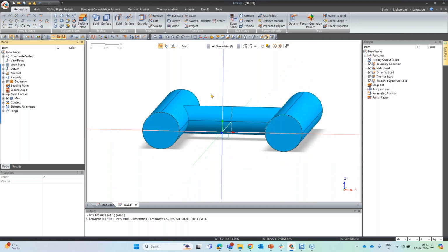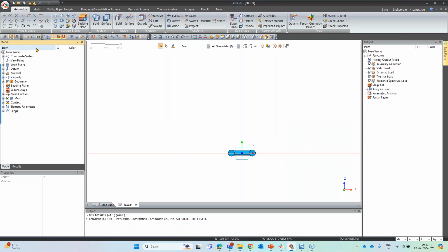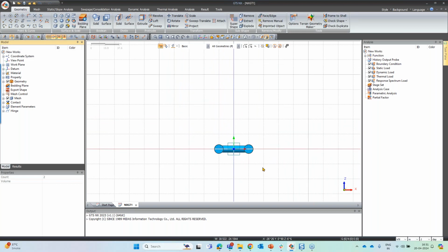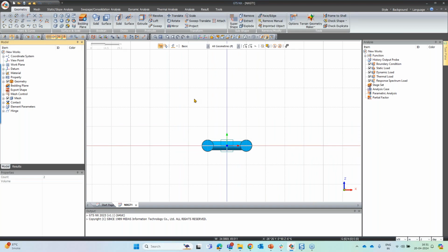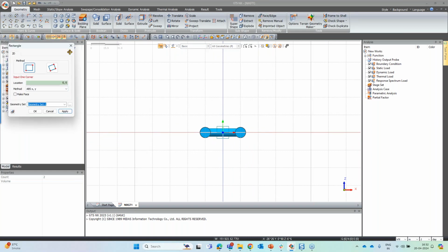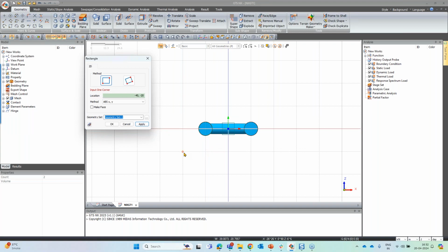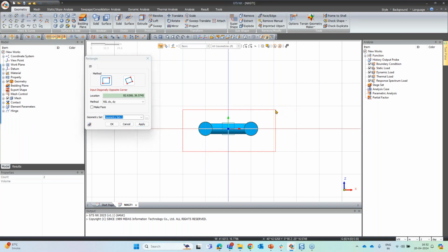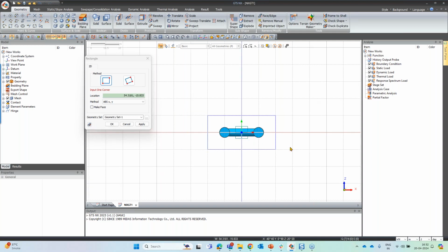Then, as we said, we are going to have the rock mass created, and this rock mass will be 200 meters in width and depth. So let's create the outline for the rock mass. So here we go. The inner rock mass which we are going to create is for a lesser mesh size, so that the stress transfer will be very good because the mesh size is finer, and then the accuracy will be much better.